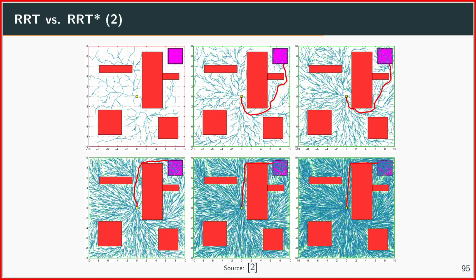And here are also some examples where we can see that this path is not constrained to be just locally optimal, but also globally optimal. This is very similar to what I talked about earlier: if we find, for example, with RRT a path which goes in the wrong direction and then we do path shortening, we will just locally improve it, but we will not make big jumps in the configuration space. And so this is exactly where RRT star can still find an optimal solution.